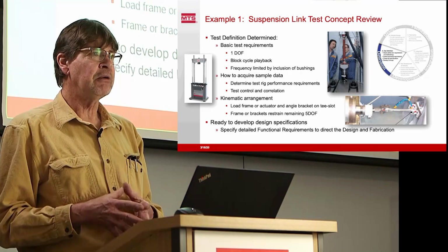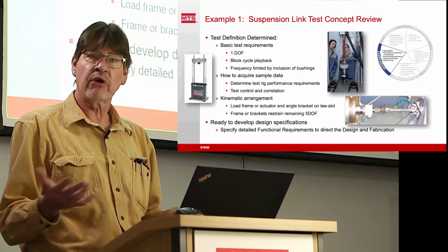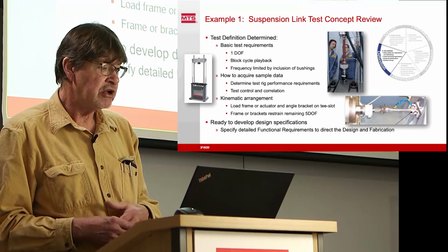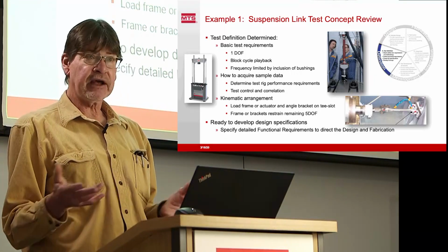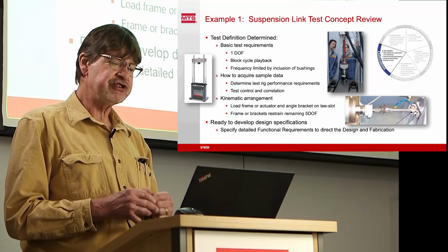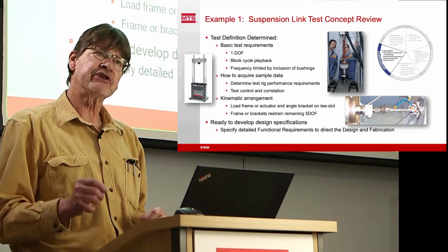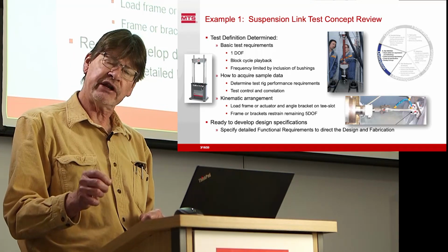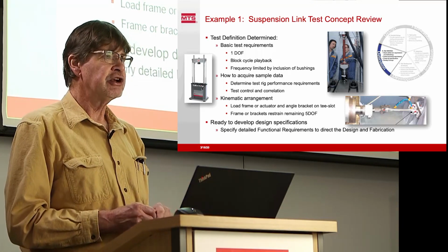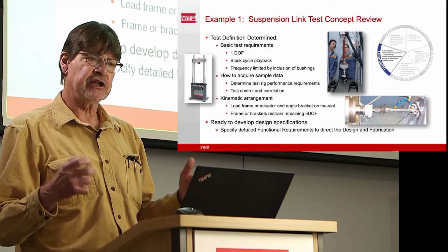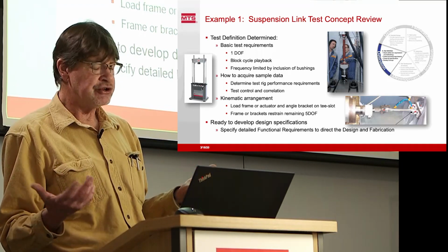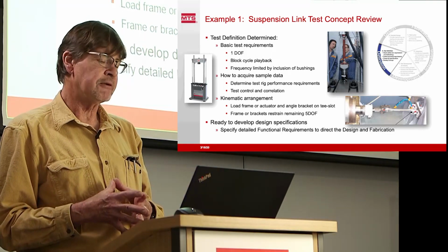There's many options available based on what our capabilities are, what equipment we've got, how much space we have. We're going to do block cycle playback. And frequency is going to be limited by the bearings. If we include the bearings in the test, then we're going to have to limit the frequency and play real-time data. If we're going to eliminate those bushings, then we can put steel plugs in the end and we can run as fast as we would like to based on the capability of our equipment.